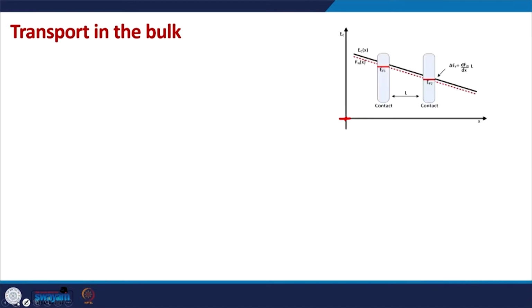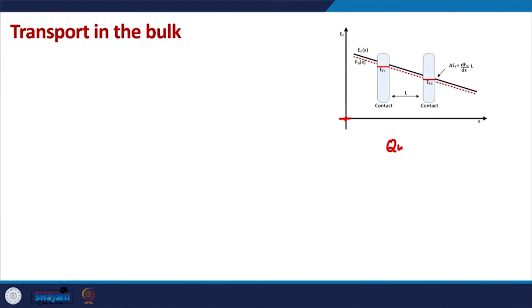So in the bulk transport case, bulk means now we have a big material, we can see it with our eyes, maybe a centimeter or a meter in length. In this case, when the current is flowing through a material, the device is not in equilibrium. So we cannot define the Fermi level as such, and this idea of quasi Fermi level is used.